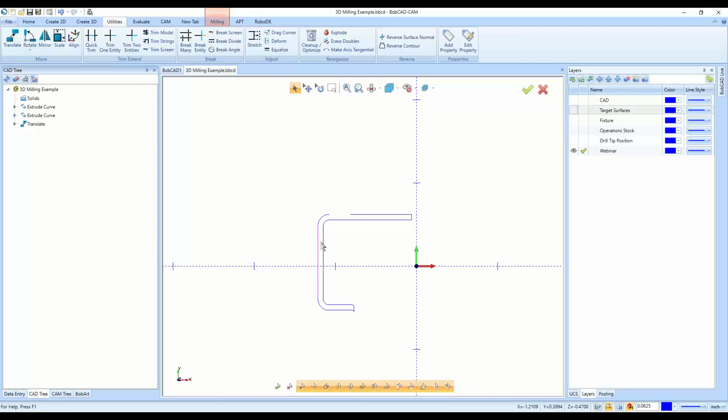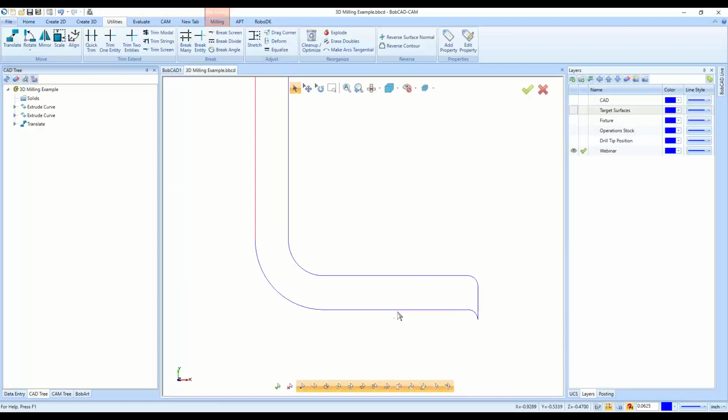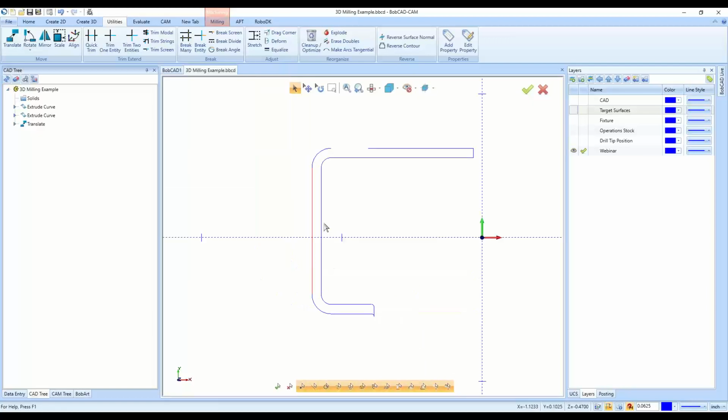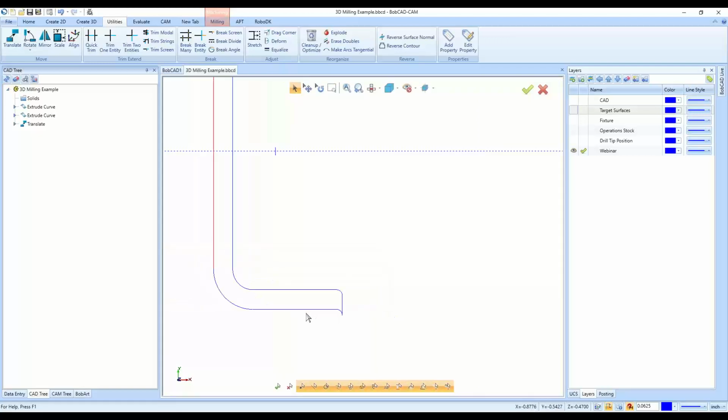If I do it the opposite way, if I hold Shift and click on this area of the line halfway, it's going to try to go around, I believe, let me make sure. Yeah, it's going to try to go around the opposite direction. It's also kind of weird because it doesn't select this arc, which can be helpful showing that there's a gap in the geometry still. So again, you want to select this entity and then make sure when you hold Shift and click that you're clicking on the specific direction you want it to go.